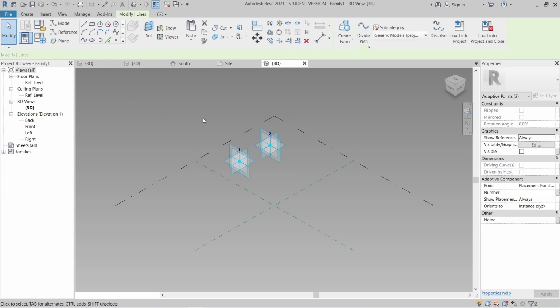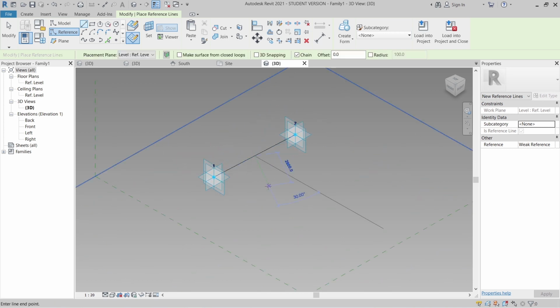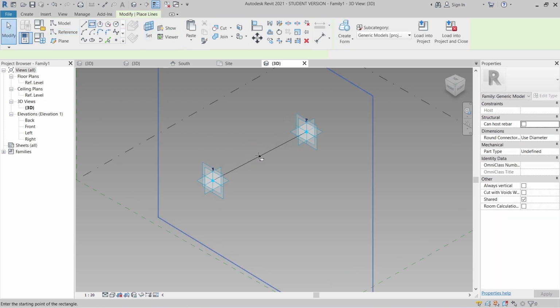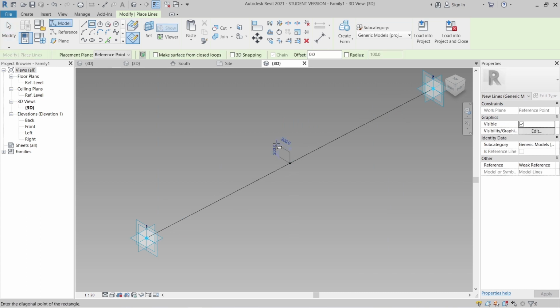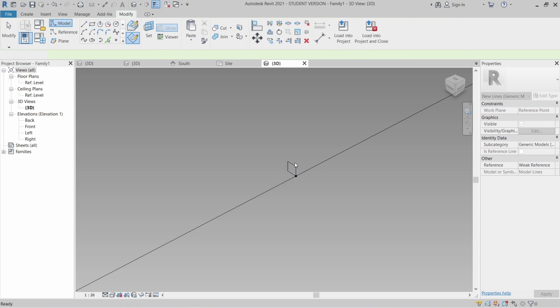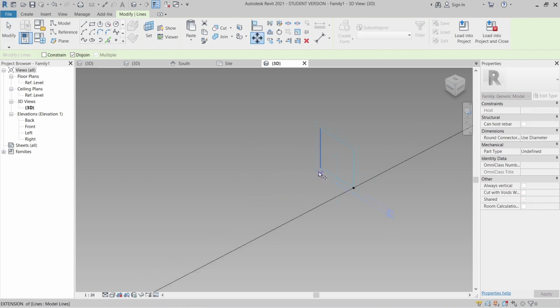Splice through point, reference point, point from here. Need two points actually. Point, hit escape a couple times. Set a plane, set for vertical using our rectangle and simply make it about something, make it like this, 100 by 100. Then select my panel there, V for move, start from here and move it until here.